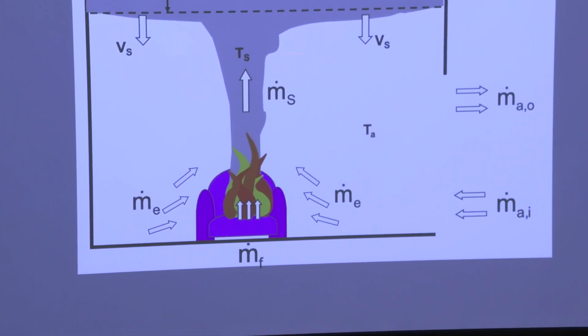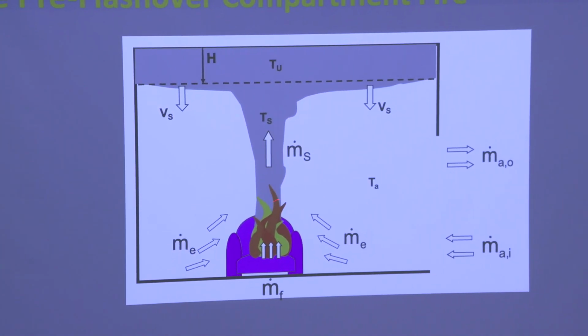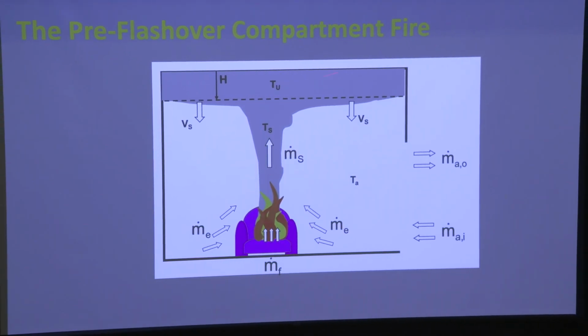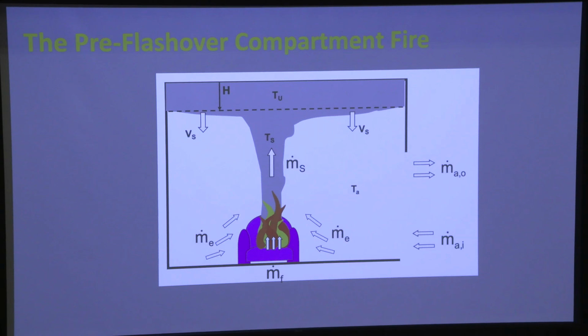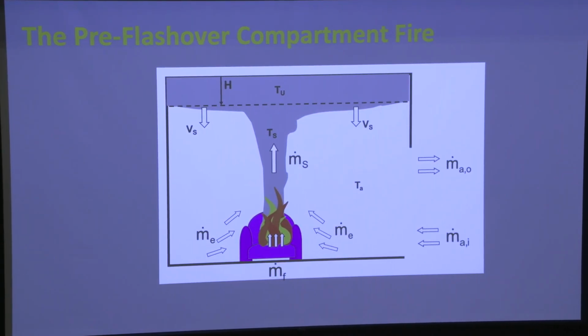but in essence, it is a solution to the three-dimensional Navier-Stokes equations, coupled with the heat exchanges happening at the flame level and potentially happening at the smoke layer. So radiation carries significant computational cost, and therefore radiation also needs to be addressed. So how do they simplify the problem?